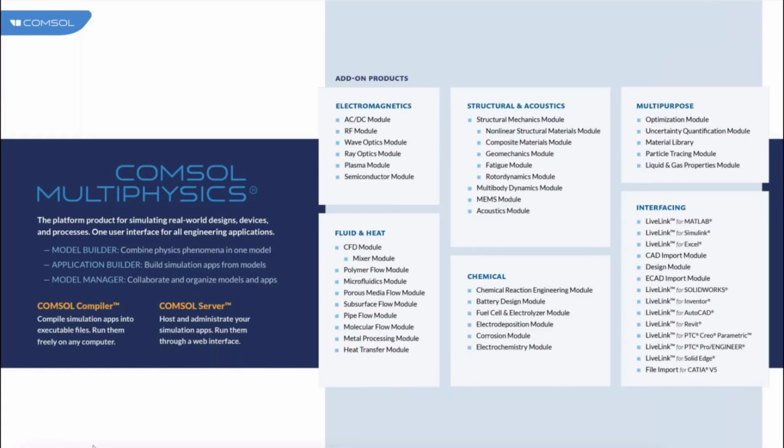On the modeling side, although COMSOL comes with a number of interfaces, you'll often want to add one or a few physics modules to enable more specialized modeling within some particular field of physics. For example, while you'll be able to do linear solid mechanics with core COMSOL Multiphysics, the Structural Mechanics Module enables you to model large nonlinear deformations, as well as beams or shells, for instance.